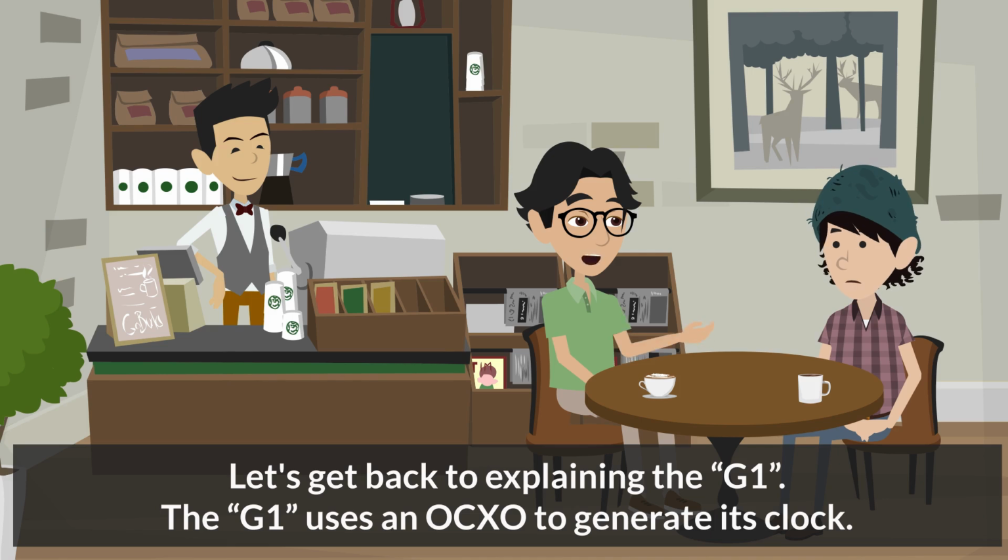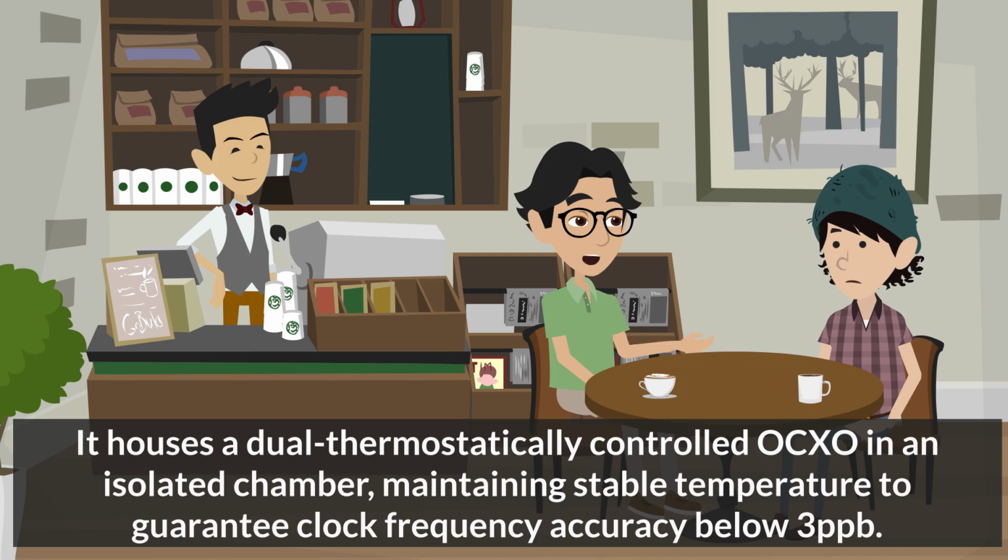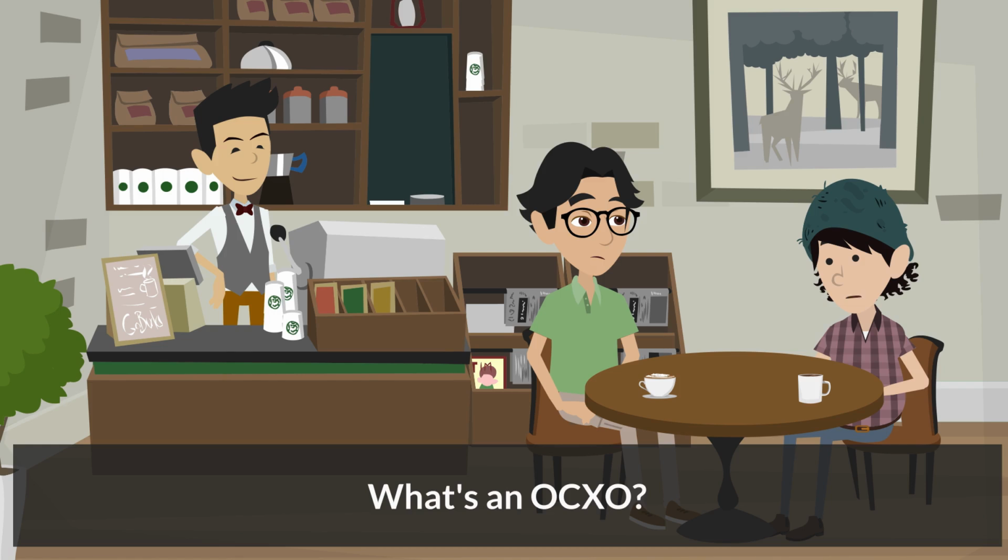Let's get back to explaining the G1. The G1 uses an OCXO to generate its clock. It houses a dual thermostatically controlled OCXO in an isolated chamber, maintaining stable temperature to guarantee clock frequency accuracy below 3 ppb. What's an OCXO?